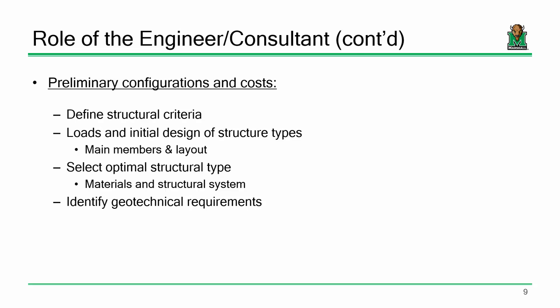Hurricane country? No, seriously. If you look at wind speed maps, you'll find that the base wind speed in the country is the same virtually everywhere except for one area, and that's along the coasts. Because along the coasts, you have higher base wind speeds due to hurricanes. Okay, so that's a scenario. What about seismic maps? Are we going to have the same ground accelerations here as we are in, say, Las Vegas or San Francisco? It's not the same story, is it? Those issues matter. Those issues determine what this building's going to look like.